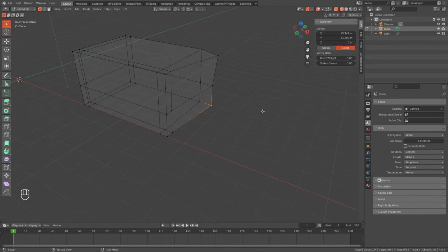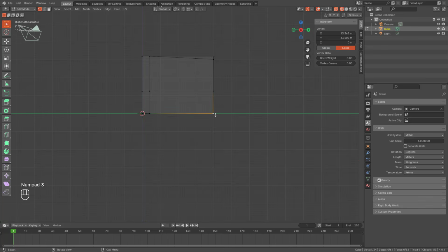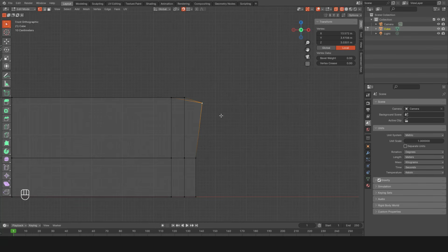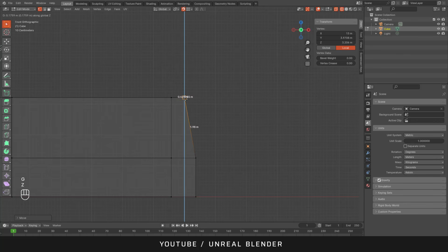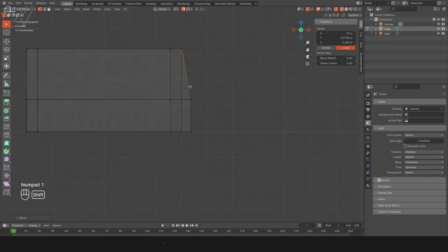You moved them by accident, or you don't know what you did, but it happens a lot. So you can do this. Select this vertex and turn on vertex snapping, and you press GX and select this vertex, GZ and select this vertex, and you snapped it in a really good place.